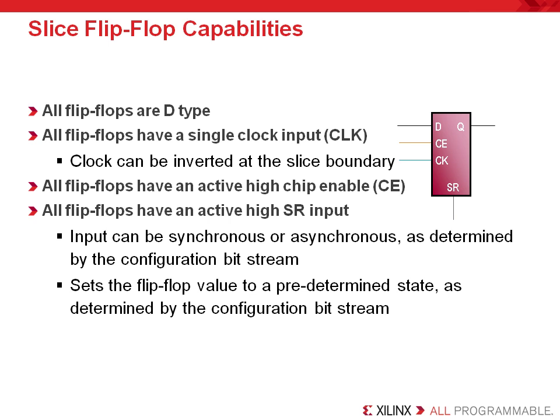Now, to help designers with this, we have made a series of Virtex-6 and Spartan-6 HDL coding style RELs that are available to you to review at your leisure. They discuss the impact of the use of your coding style and provide you with many good design practices that will help you get high performance and high device utilization. So check those out. Even if you're using the 7 series, these techniques will still apply to the 7 series.